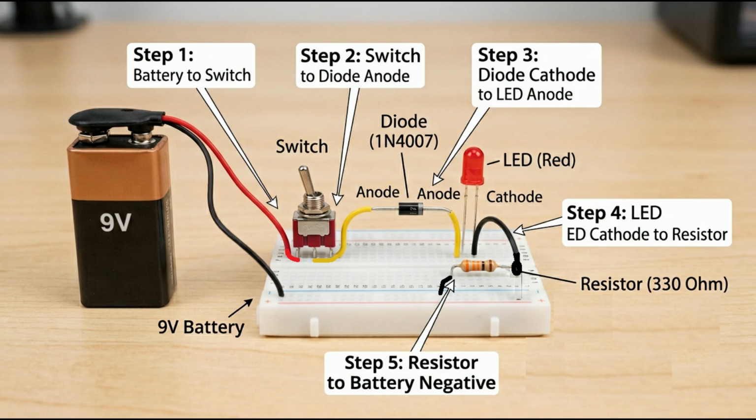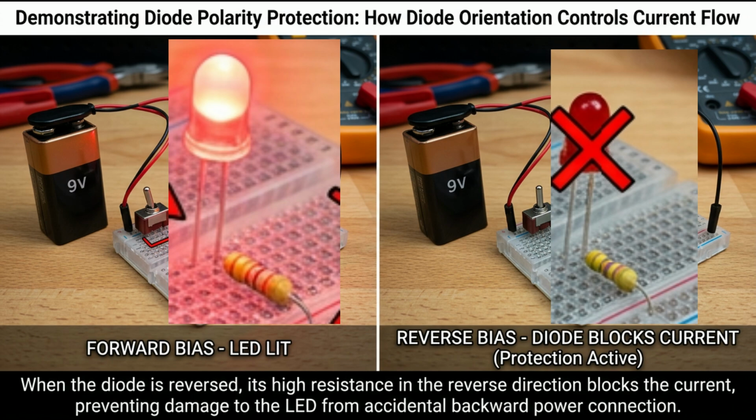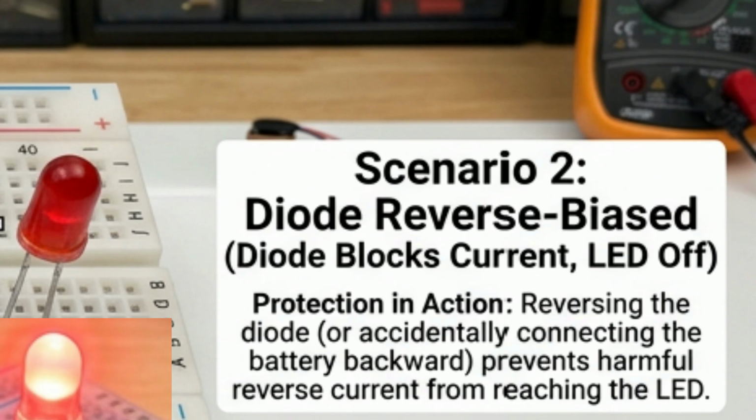When you close the switch or connect power, the LED lights up brightly because current flows through the diode forward, then through the LED and back. Now try reversing the diode. Swap its two ends. The LED will not light up at all because the diode blocks the current. This shows protection in action. If you accidentally connect the battery backward, the diode stops harmful reverse current from damaging the LED.